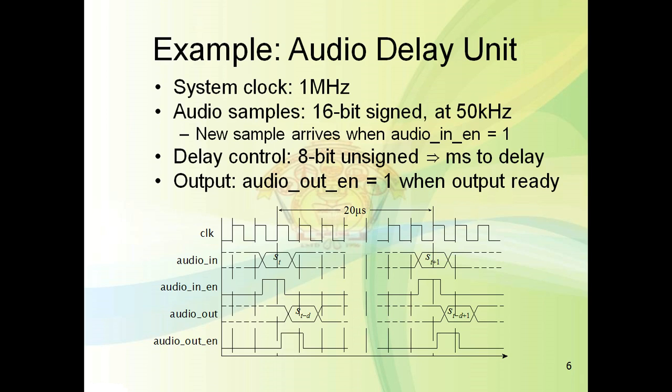In the same way, the delay time is determined by an 8-bit unsigned input representing the number of milliseconds of the delay. The system clock frequency is 1 MHz.